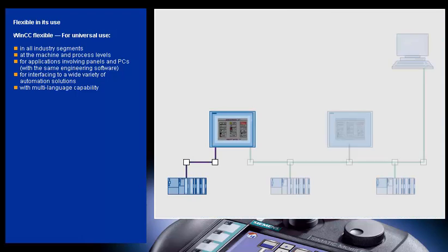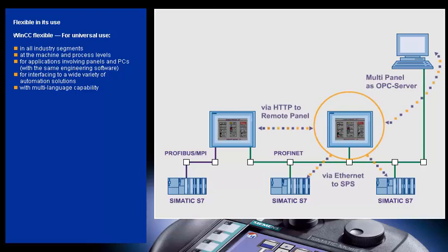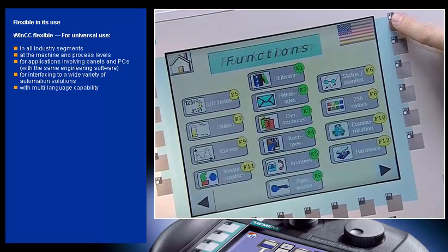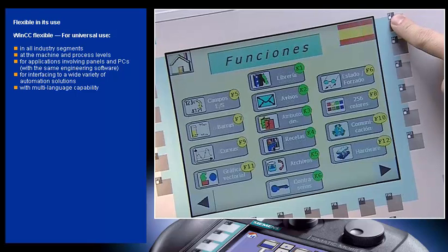Interfacing to SCADA S7 over PPI, MPI, Profibus, and Profinet, possible links to CMotion and CNumeric, third-party connectivity, and vendor-independent communication via OPC ensure the right connections in a wide variety of automation solutions. Multi-language engineering software offers the best prerequisite for worldwide use of WinCC Flexible. Projects can be created in up to 32 languages, as many as 16 of which can be used simultaneously online. Machine and plant builders who export worldwide profit particularly from our web-based service concepts.